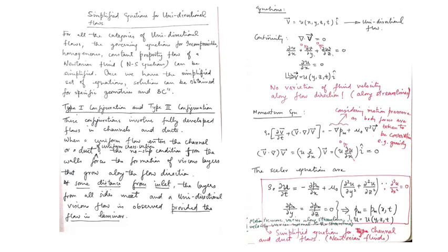So the advantage of this simple analysis is that whenever later on we will show you some solutions involving channels and ducts, there my starting point would be the ending point that I have here. That means the simplified equations that I have now obtained with whatever characteristics on the velocity and motion pressure, they can be just taken from here, and solution may be carried out for any specific channel or duct flow.